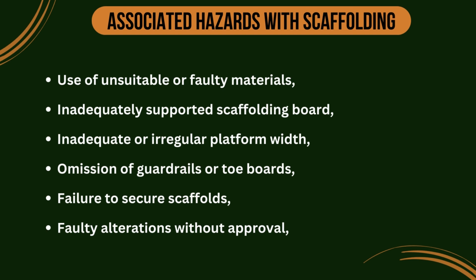Then it is very important that whenever you want any alteration in the scaffold, basically you should have proper and prior approval for that, because these scaffolds are designed basically keeping in view the loads and the forces coming over them, and any alteration without keeping in view the design aspects may be very dangerous.